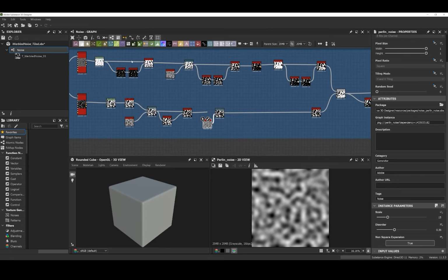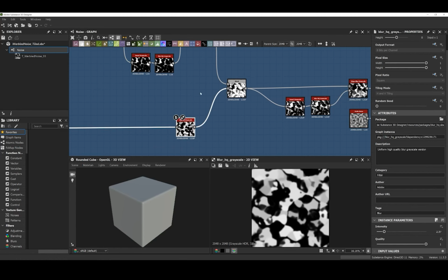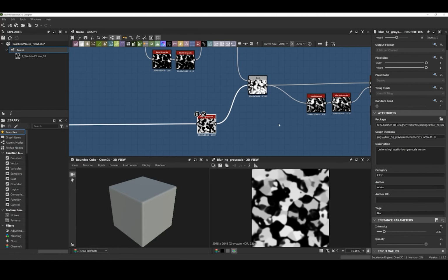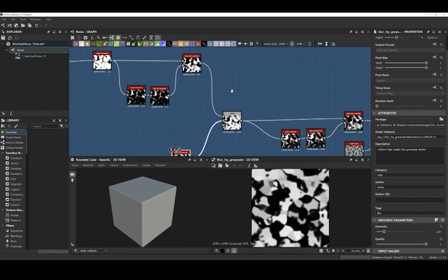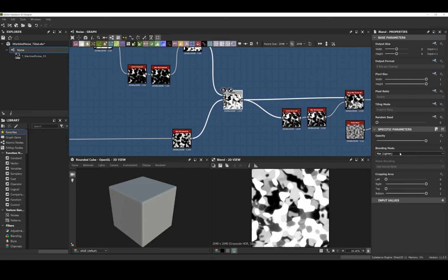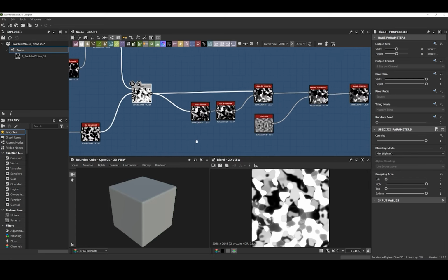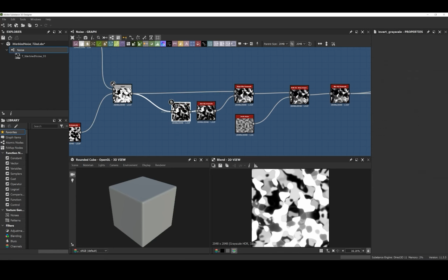And so you can see a lot of this is very similar. I'm using a lot of the same techniques to continue to find the shape of this texture. Sending it into a blur again, and that intensity is around 2.37, and then I'm just blending those two together with a max lighten. And that's giving me this nice erratic shape pattern here. So a goal is eventually to get to something very organic looking.